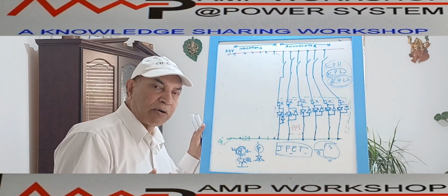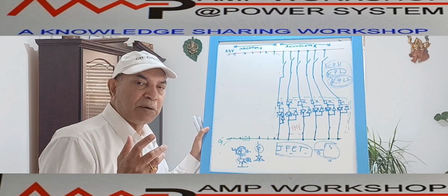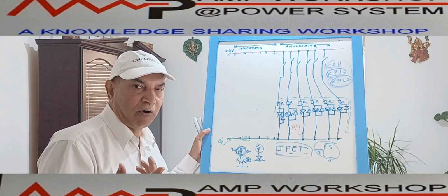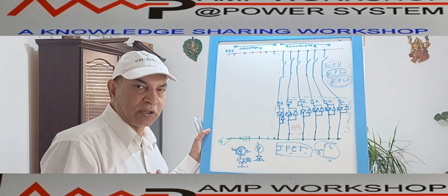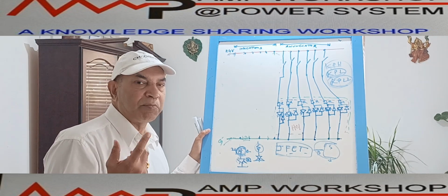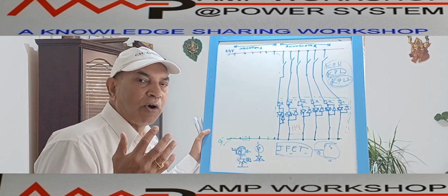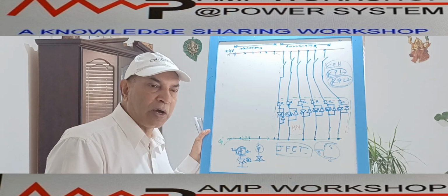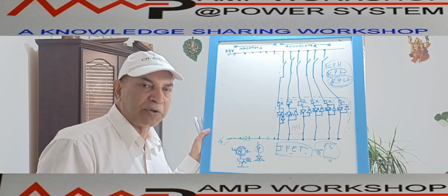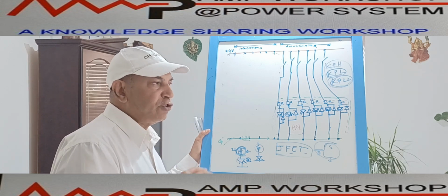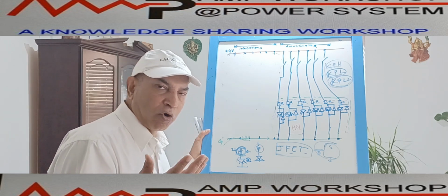So the first abnormal condition is, suppose the breaker is tripped on fault. That is the abnormal condition. There is a fault on the circuit. So for breaker trip, we have to monitor that the breaker is tripped. So how is the breaker trip monitored? We monitor the circuit breaker's or the circuit's abnormal operation by protection relay, as I discussed before. So protection relay ultimately stands for the lockout relay.